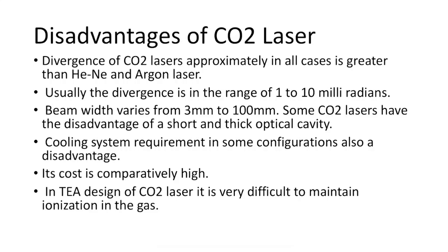Some CO2 lasers have the disadvantage of a shorter and thick optical cavity. A cooling system requirement in some configurations is also a disadvantage. Its cost is comparatively high. In the TEA design of CO2 laser, it is very difficult to maintain ionization in the gas.